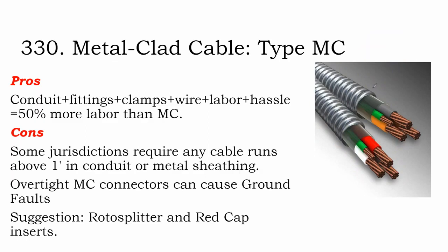If you put this in a larger tube, so that you have the empty space to pull this cable through, these ridges and the flexibility of the cable both make it very difficult to pull cable through this stuff. And so you get a hollow flexible metal conduit for short sections where you're pulling single conductor cables through. But because this is more tightly wound around the cables themselves, you get more flexibility in this.